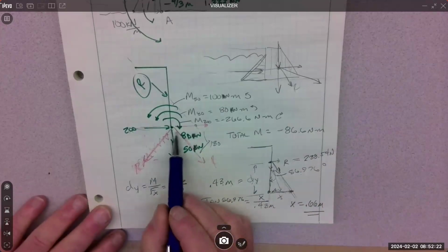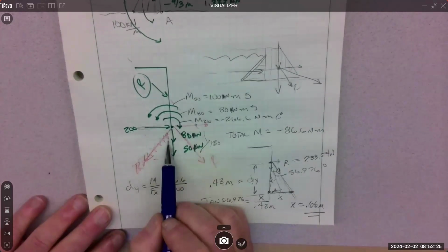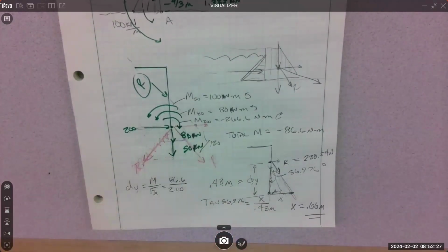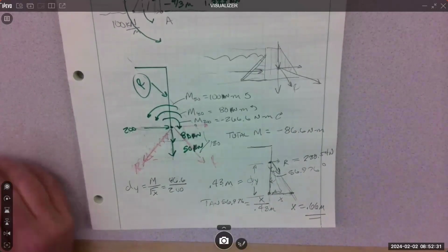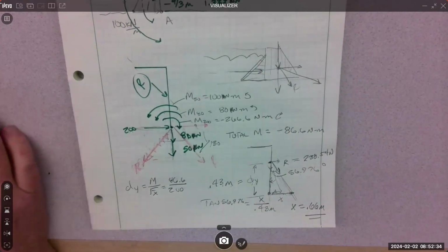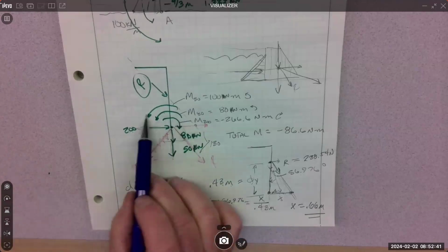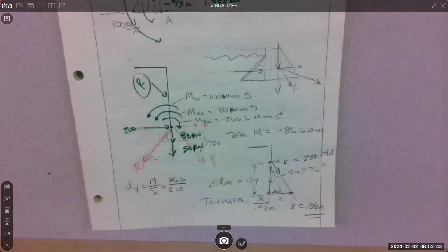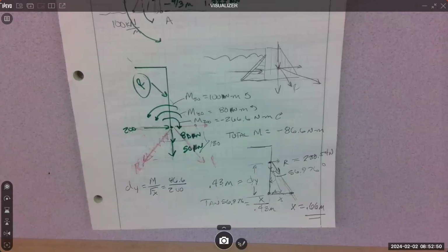So this thing has got to have some kind of support underground, and that would tell me that we need to be at least 1 meter each side of the pole. So that's a big area of concrete, but it's carrying a huge load, like these are big loads. Big twisting moments, right? These moments are trying to tip this thing over. So some substantial supports needed. Boom. Awesome homework right there.